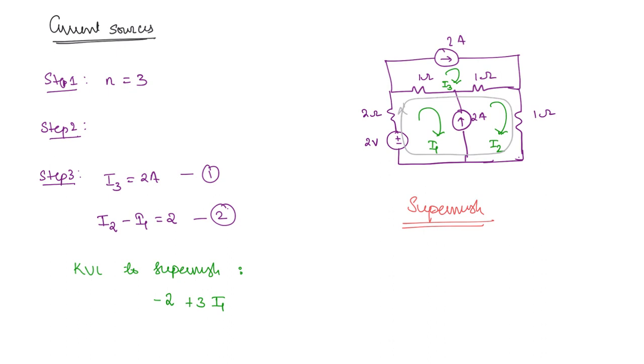Now for these two resistors, the current that is associated is I2, so 1 plus 1 into I2, and you get plus 2 I2. But through this 1 ohm, I3 is also flowing. Through this 1 ohm also I3 is flowing, so we will have to incorporate that also. We are going in this direction and I3 is flowing in the opposite direction, so minus I3. Similarly, here through the 1 ohm also I3 is flowing in the opposite direction to what we are taking, so it is going to be another I3. So I will write here minus 2 I3. This is going to be 0.